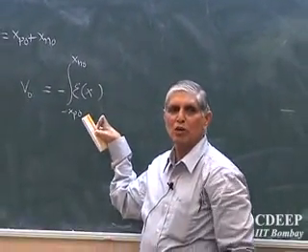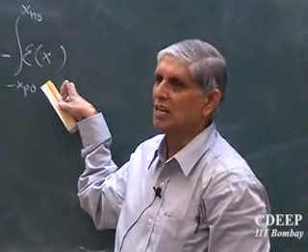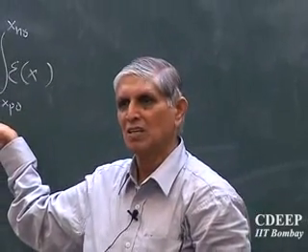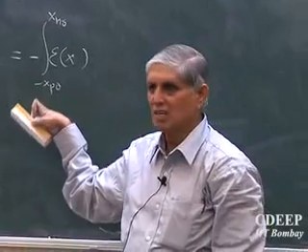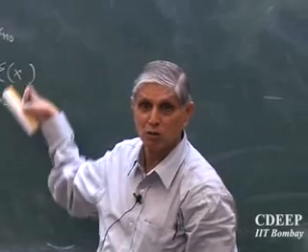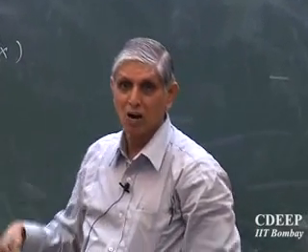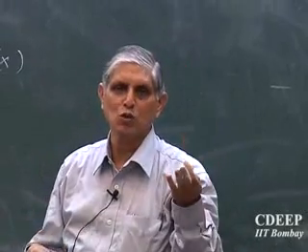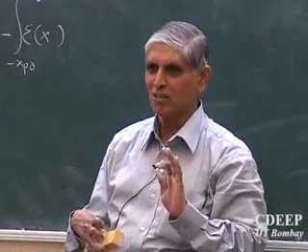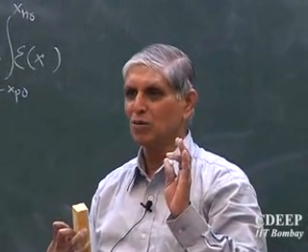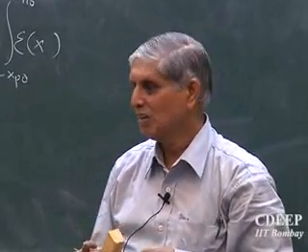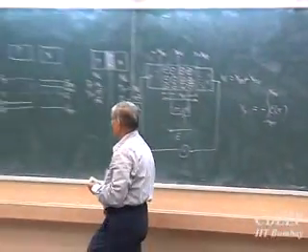So our aim should be, what should I first find out? The electric field. If I get the electric field across the junction, then I can always evaluate the voltage across the junction. Is that clear? Now, in the band diagram, what is it translating into? A built-in voltage, or built-in field, means energy change. qV0 is energy. Is that correct? So if there is a built-in voltage between P and N, obviously there must be an energy change between P and N, and it should show up in the band diagram. So let us go back and look at this figure again.